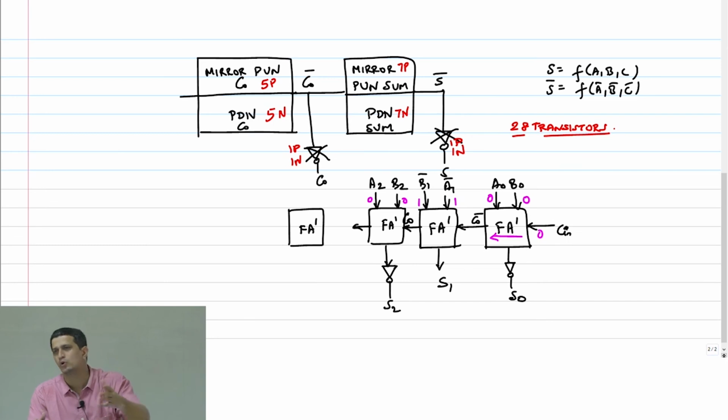So as a thumb rule, you upsize it by a factor of 3 or 4 and then repeat that adder, your delay will be okay. This is an empirical thing that has been found and it reasonably works. That's why I asked you to upsize the carry out circuit alone. Some I don't have to do it because it appears only once in the critical path delay term. So the sum is left as a regular circuit, in the sense the sizing is just the usual sizing that we get. Okay.